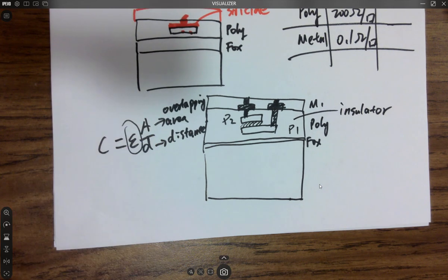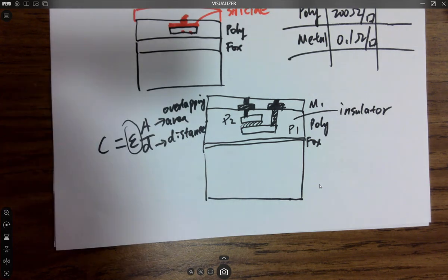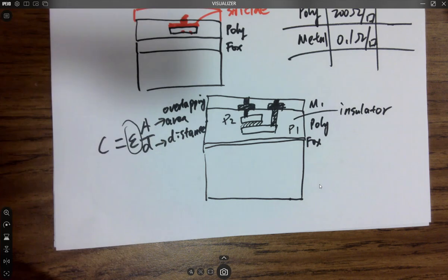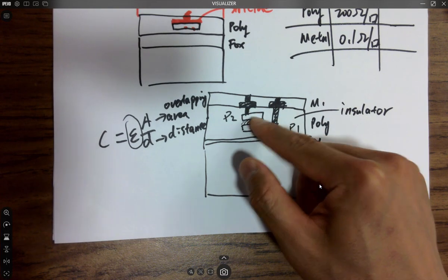So there will be a parameter telling you the sheet capacitance. There will be a parameter table you can look up, right? So a 10 micron by 10 micron area gives you several hundred picofarads. You can use that one, and consider multiples of that area in order to generate various amounts of capacitance from that overlapping area. Can you imagine this is two plates and two connectors? So it's forming a capacitor in the middle.